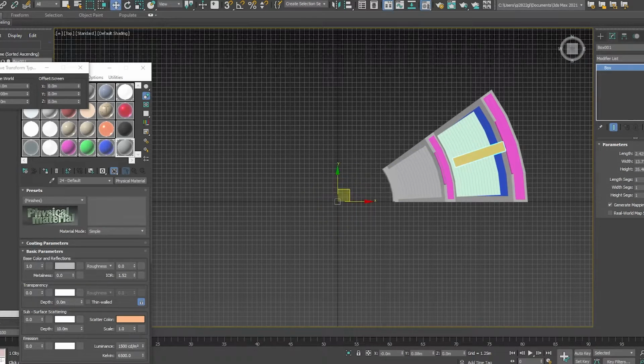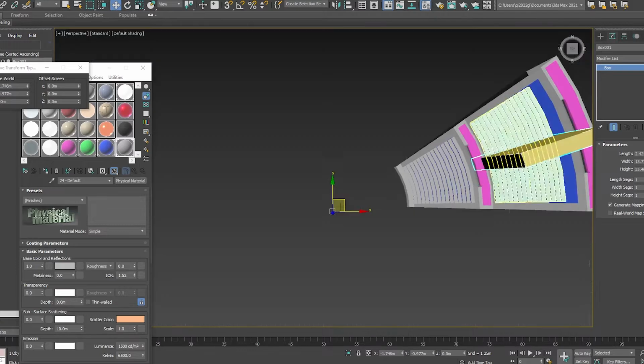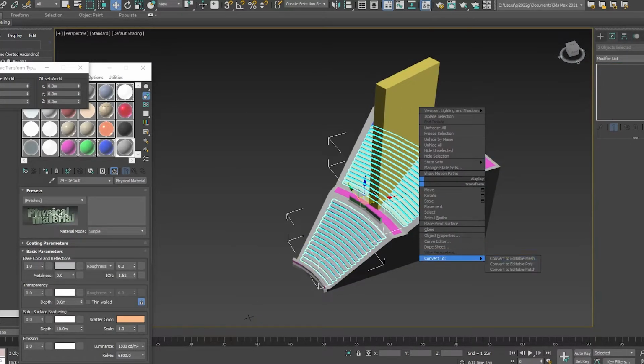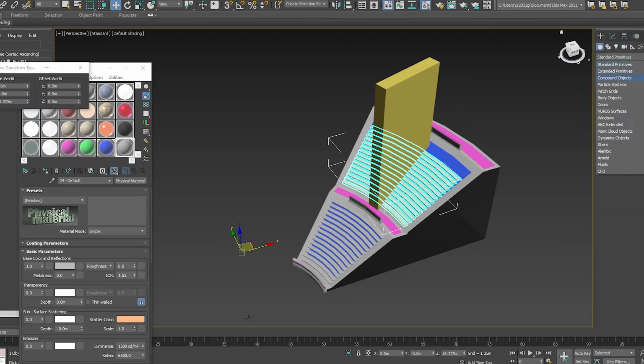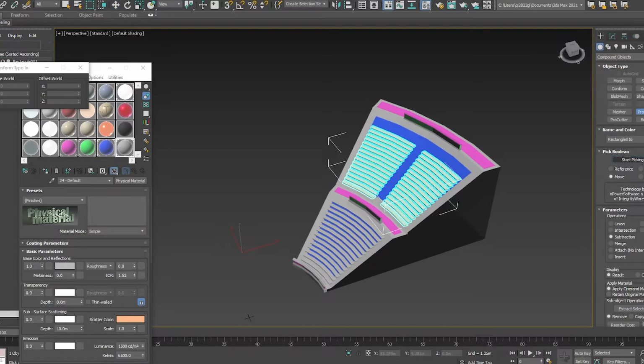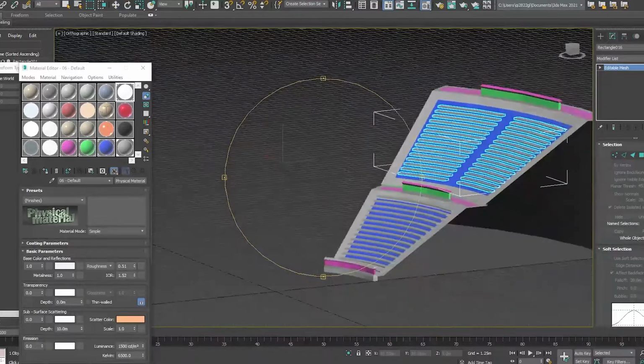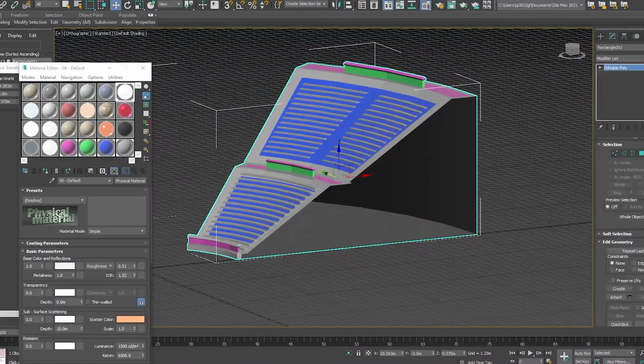So I create this block, and I move the origin of the block to 0, 0, 0 so that I can have it rotate along that same curve as the seats. And then I do a Boolean subtraction. Boolean subtractions, Boolean unions, Boolean operations. They're one of the main arrows in the modeling quiver that I use for alt space.